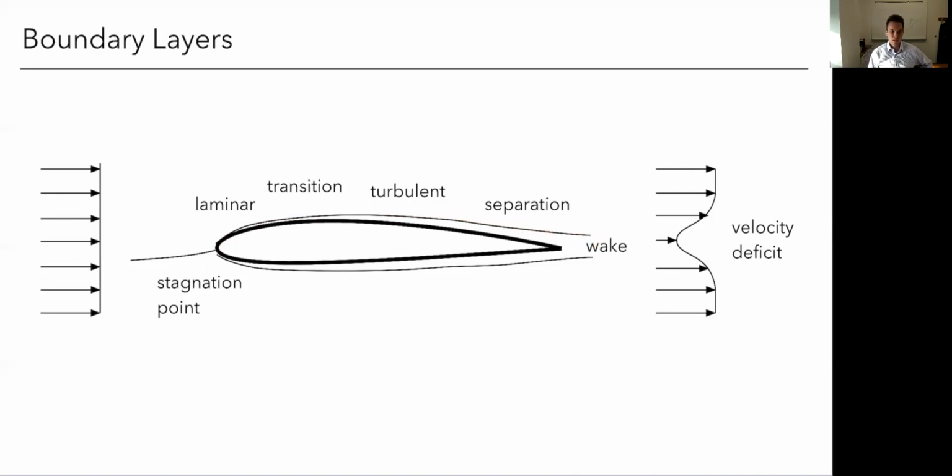So you can see depicted here both skin friction drag and pressure drag, right? The skin friction drag is the drag due to the fluid moving across the body from shear stress. The pressure drag is really the difference between my velocity profile upstream and downstream. Because of that wake, I have a velocity deficit. So I've got this high pressure here, low pressure here, I've got a drag.